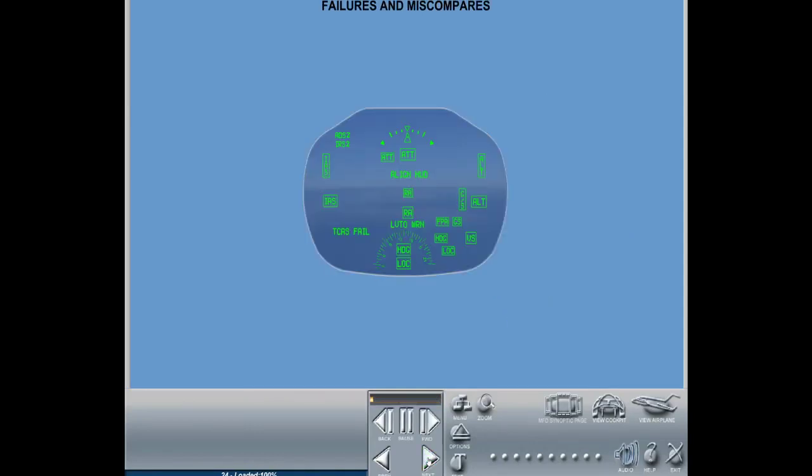Failure flags. Failure flags are displayed for invalid sensor status. It is usually indicated as large-size boxed characters. It will flash for 10 seconds and then become steady.